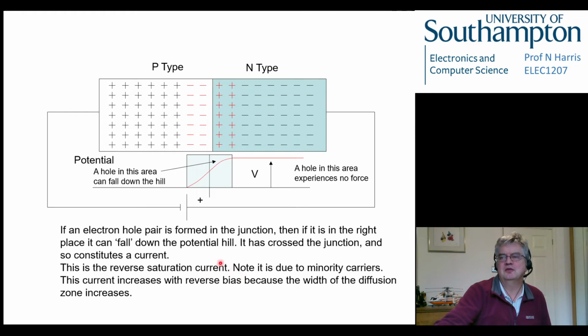So if you imagine that the solar cell is effectively a big p-n junction, when light falls on the junction, it gives it a bit more energy, and this causes more of these electron hole combinations to occur. So an electron gets kicked into a high orbit and then gets whizzed away by the potential. And so as things get hotter, you'll find this reverse saturation current, this leakage current if you like, gets bigger. So that's the nature of reverse currents in these devices as well.